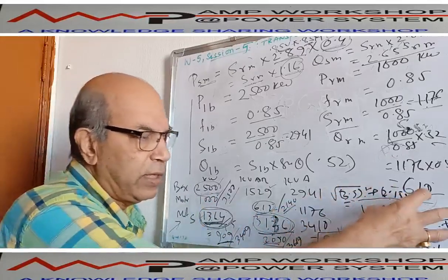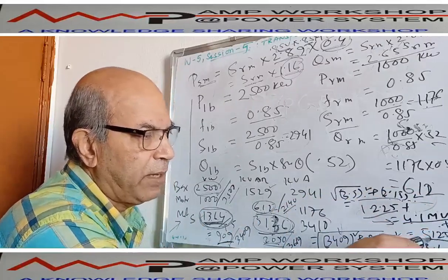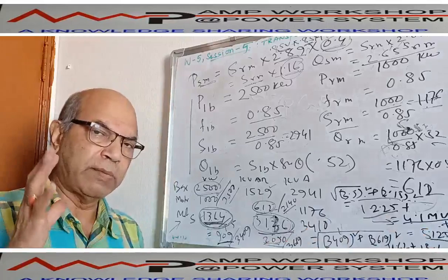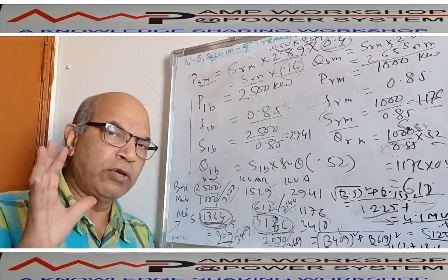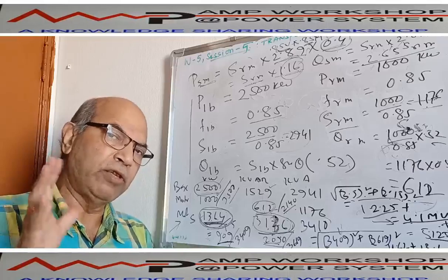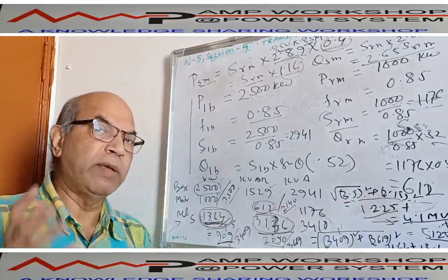So I have considered in the overall transformer a 20% margin. At the final size it is coming 5 or simply 5 MVA transformer required to cater for the normal load during running condition with a 20% future margin. But with this capacity, I don't know whether the motor will be starting or not.